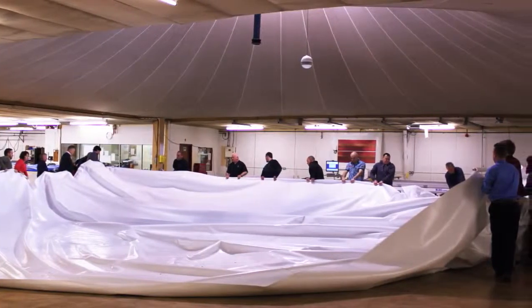At the point of design, we go through computer modelling, analysis with form finding, patterning of the material. After patterning, the basic fabric form shape is taken to the cutter plotter, which is behind me, is cut and then welded together.